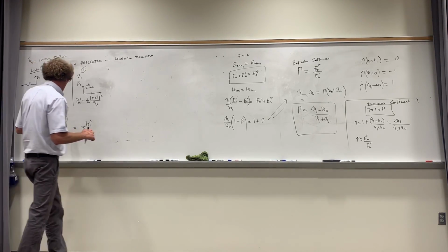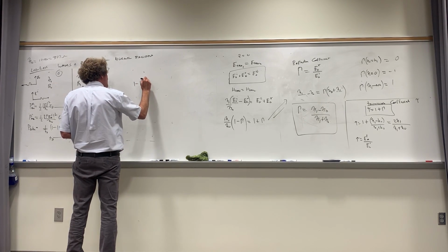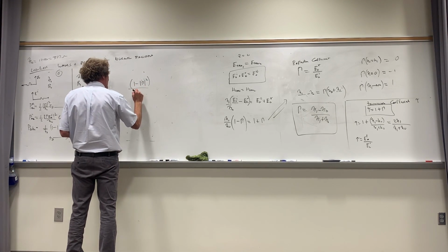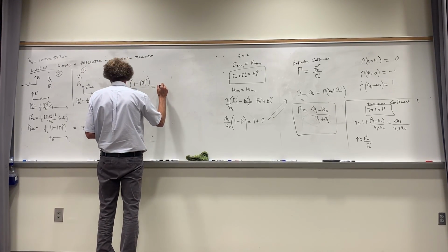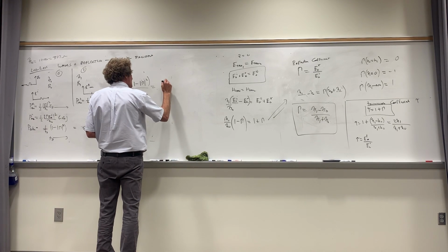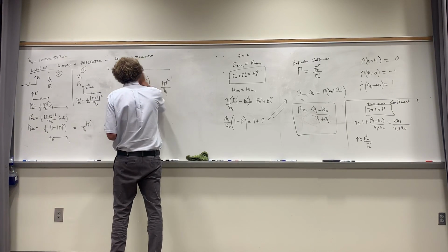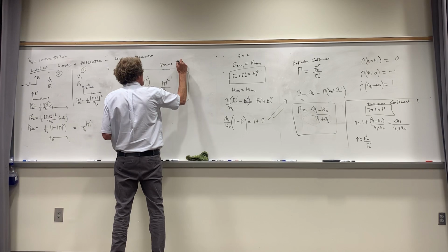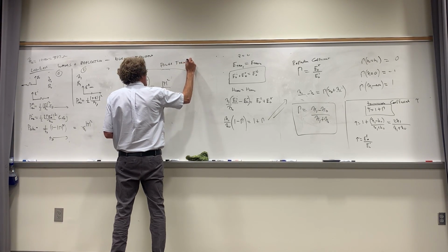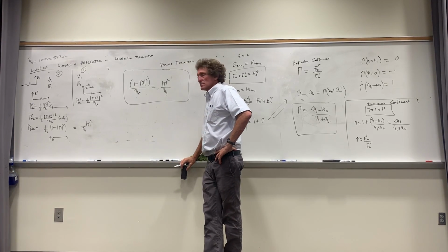So now you can say this for power transfer. You can say 1 minus the magnitude of the reflection coefficient squared, divided by eta naught, is equal to the transmission coefficient squared over eta 1. And this is true because it's for power transmission. In fact, it's normally incident power transmission. Are you with me, class? And that's important.